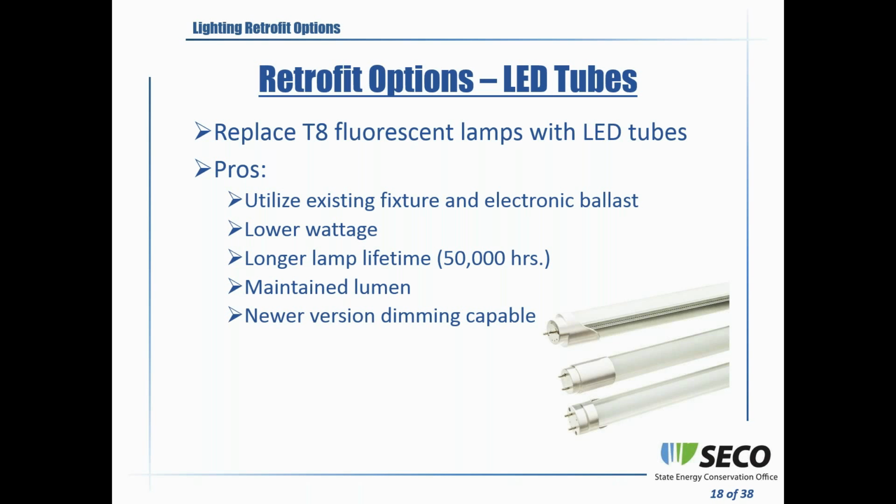And the newer versions of these lamps are coming in where they could be directly dimmable also, basically. So if you've got a dimming system, you could put these lamps in there, and you'll be able to dim it and so on and so forth. So these are the pros. The cons are the cost. So initial cost compared to the T8s, the lamp cost is a little higher, and the ballast compatibility issue is something you need to watch out for.